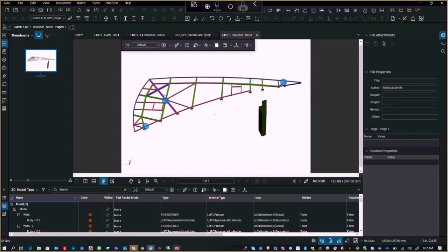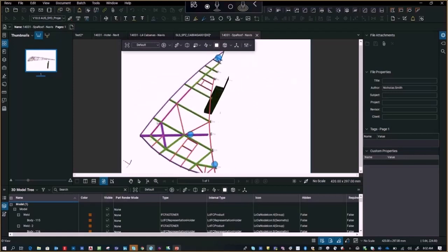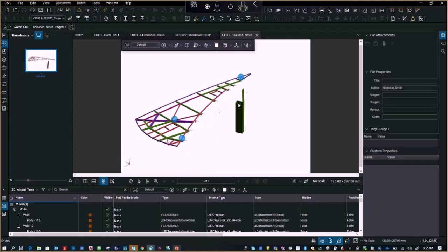So you can do a complete quantity takeoff from the IFC if you're trying to figure out what your concrete quantities are, and even start applying formulas where your rate. You can just count the downlights, for example, in the building. All the downlights.